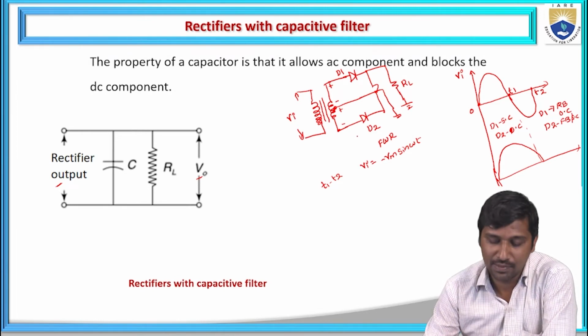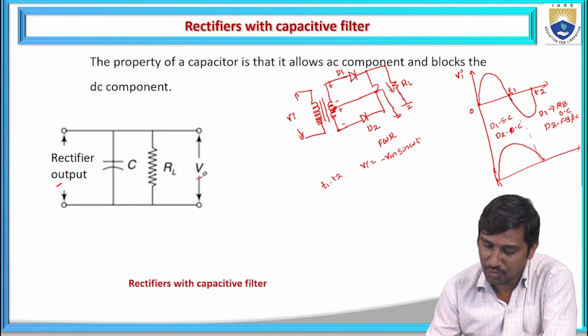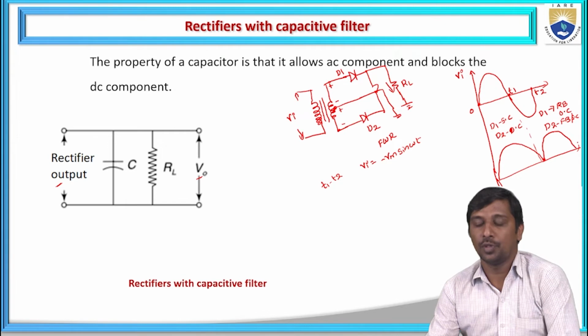The maximum current now passes through the short circuit path, that is D2, towards the load resistance. For the positive peak cycle and the negative peak cycle, the current flowing direction across the load resistance is the same. Hence under this T1 to T2 interval also, it allows the same amount of output voltage.